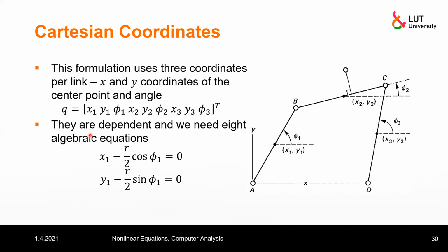How to write those constraint equations? Those equations are about the joints here, in those points. Because the equation written here says that this vector is equal to 0. So this is that equation. It means x minus r2 cosine phi. If you analyze it carefully, this is the vector that points to A. So this is the vector for that joint.